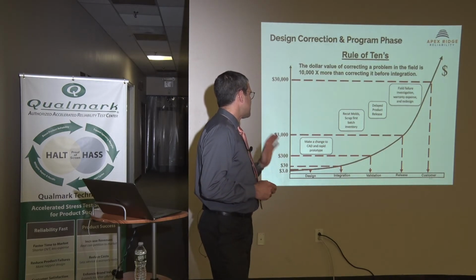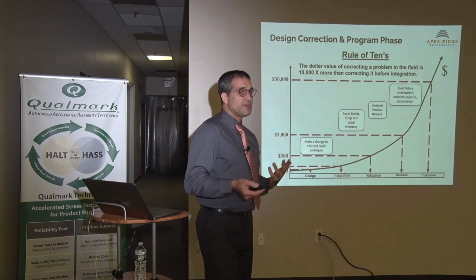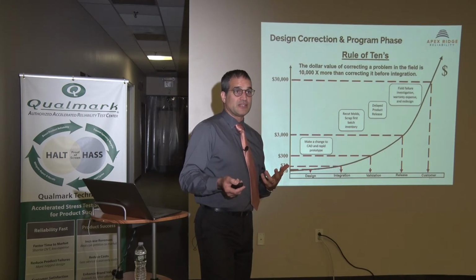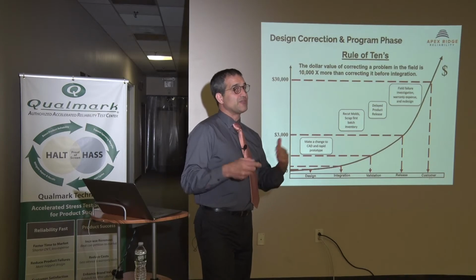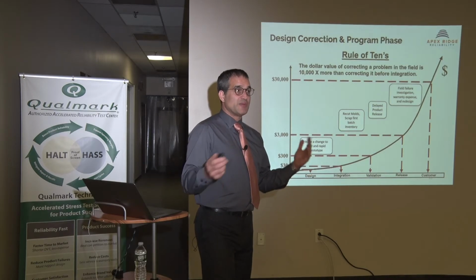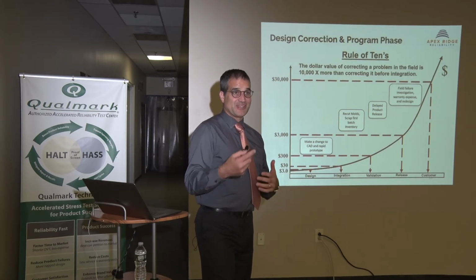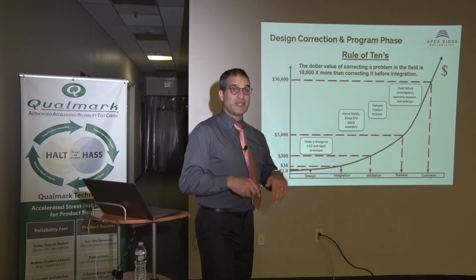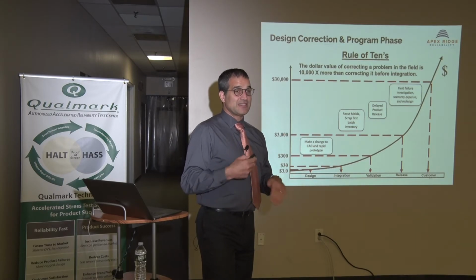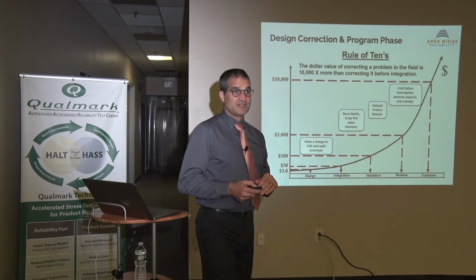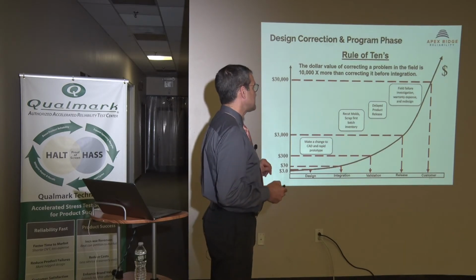Then if you were to catch it later in integration, you might be actually scrapping molds that you made. Right? This can get very expensive. And you've also had a lot of other processes and systems made around that design, manufacturing, cost reduction, and those might have to be changed too. You can see how that easily could be 10 times more in cost. Well, then let's go on to the next.